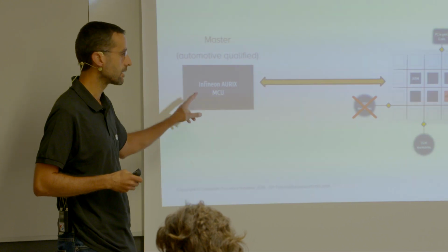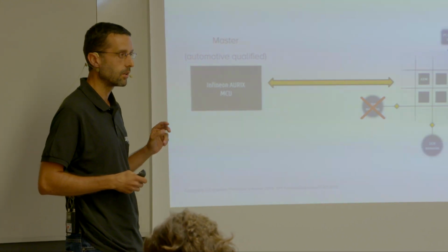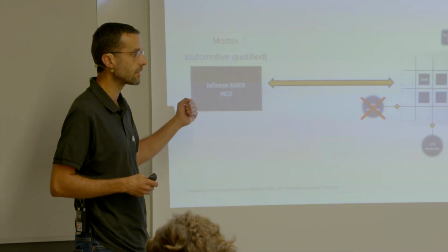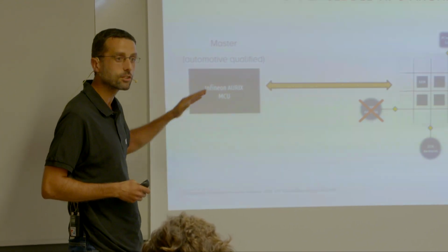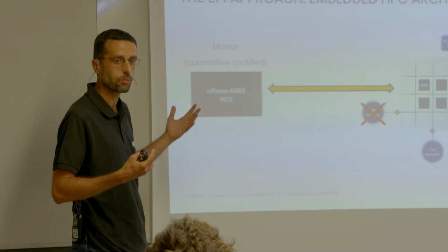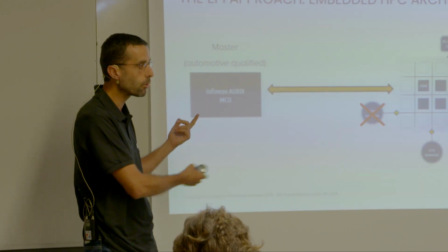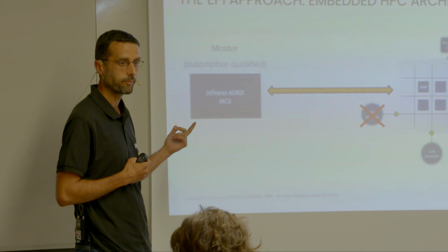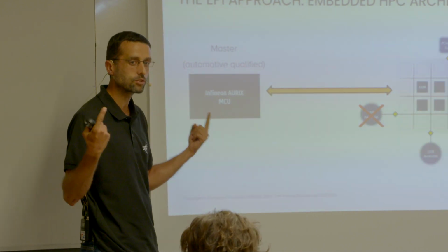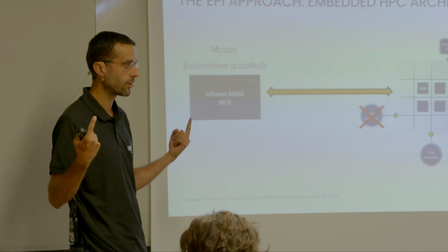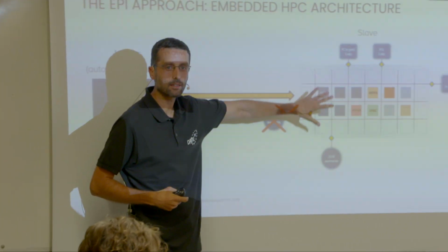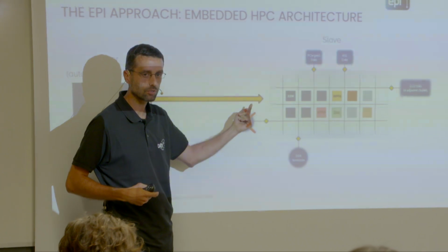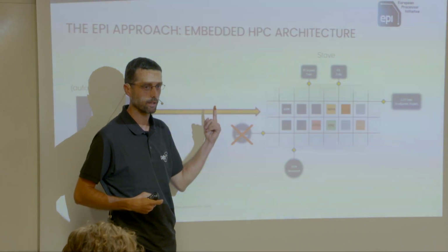Normally, these systems need two independent clocks. Why? Because you need to be sure that if the processor has a problem in the clock and gets completely stalled, there's someone noticing and being able to reset the system, okay? This means two different sources of clock for the time. Here, for instance, you may have different time domains, but the source for the clock will be one.